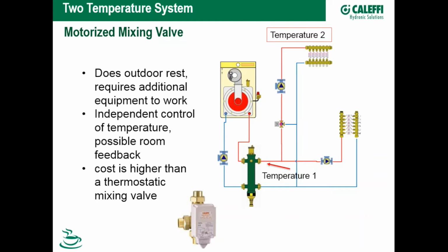Now, the downside. It's valve, it's motor, it's control. It's installation work, it's setup. So the installed cost of a motorized mixing valve is always going to be considerably higher than doing a thermostatic mixing valve.